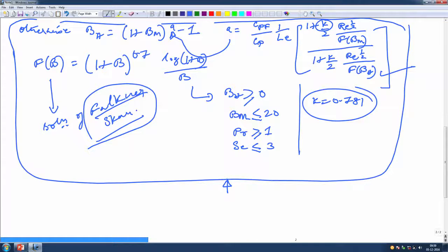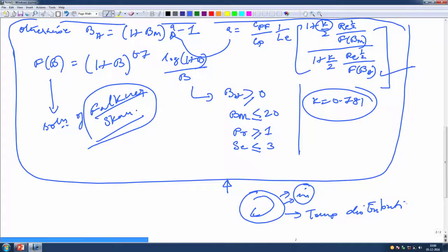Now, obviously we have done this, we know what the heat and mass transfer is, but there is a certain catch now. People may be interested to know what is happening within the liquid phase itself. Why is that important? Say you have a liquid, and you may not be just interested in that m dot. m dot is a global parameter. You may also want to know how the heat and mass transfer is happening within this droplet. That means what is the temperature distribution, and what do the flow profiles look like? How does it vary during the droplet lifetime?